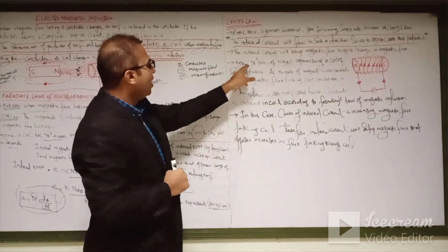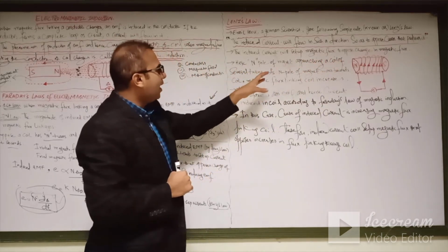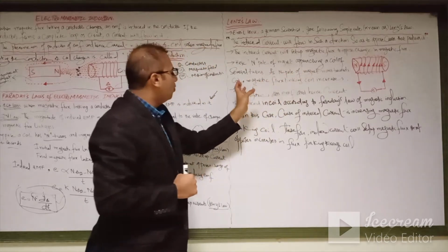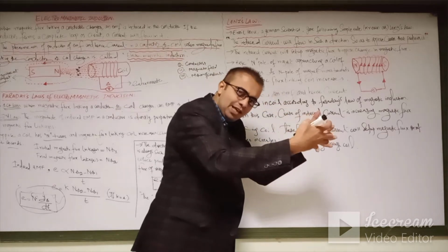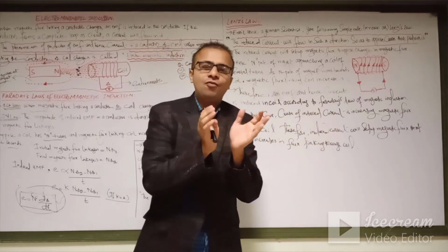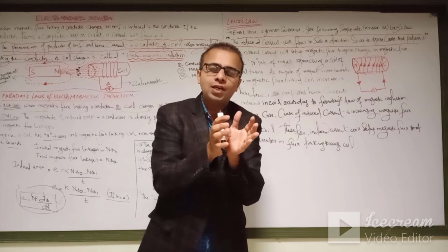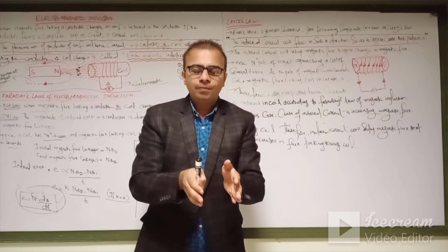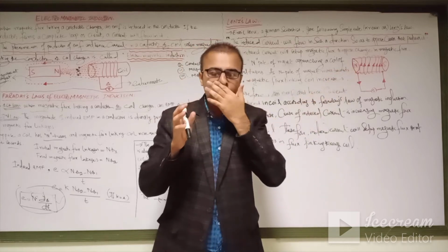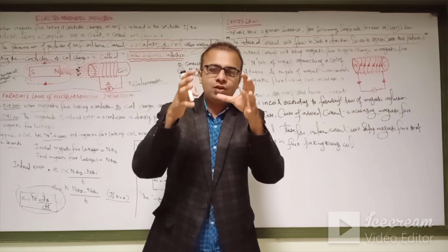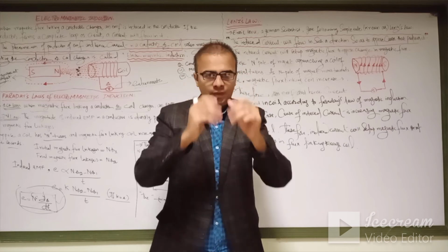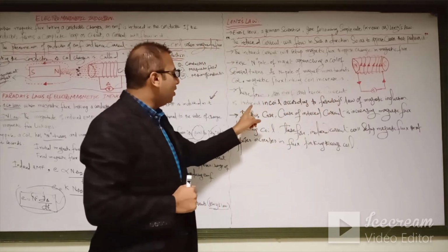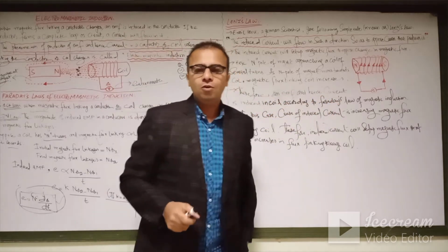Here the N pole of the magnet is approaching the coil which has several turns, the N pole moves towards the coil, and the magnetic flux linking with the coil is increasing. If the magnetism is stronger, then obviously the magnetic flux and magnetic field will be greater, and hence the EMF produced in the coil, or in the turns of wire within the conductors, will be maximum. Therefore an EMF and hence currents are induced in a coil according to Faraday's law of electromagnetic induction.